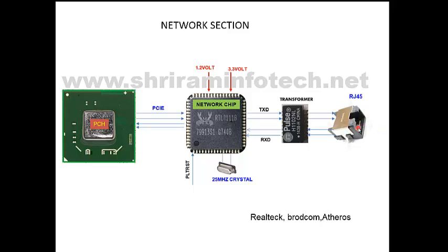Now if the connector is proper but the ping commands are not going, then you have to open the motherboard. Of course, before that you have to check the drivers also. The driver should be proper. If the driver is proper but still the network is not working, then open the laptop and locate the chip. This chip is normally made by Realtek, Broadcom or Atheros, either of these. It is very easy to locate the network chip.